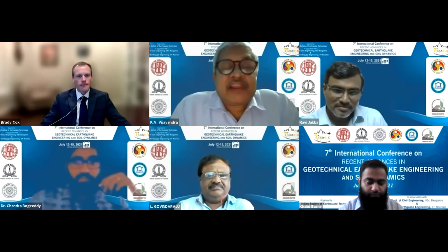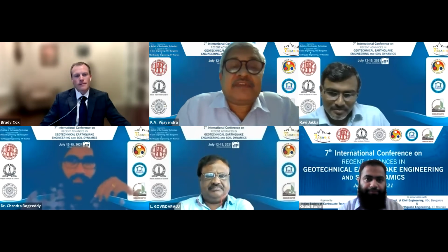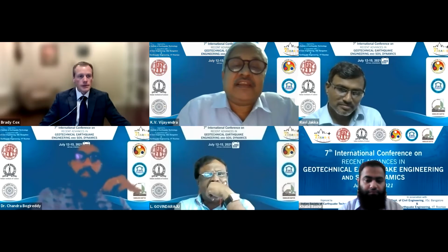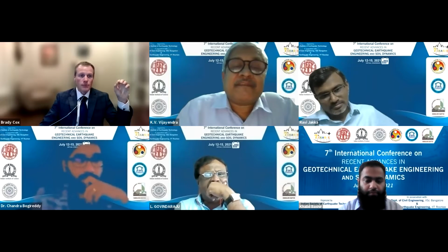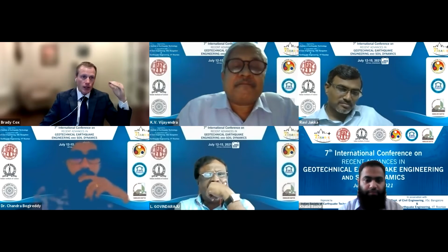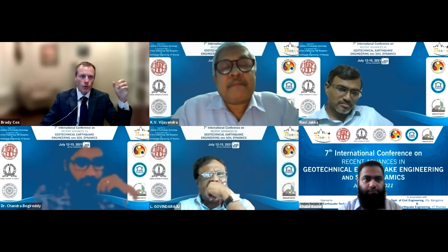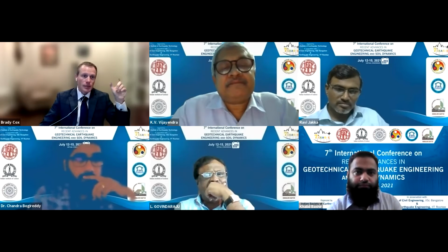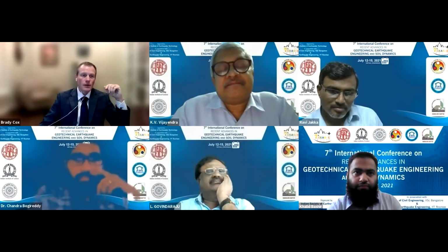Thank you. One last question, Professor Cox. In the shear wave velocity profile which you adopted to get the transfer function, what was the minimum damping ratio used? Was it from Stokoe and Darendeli? Yes, that's correct. When we did our normal 1D site response analyses without modifying damping, we used D-min from Stokoe and Darendeli, so it varied as a function of material type and confining pressure. D-min would typically have been on the order of 1% to 2%, depending on whether it was clay or sand. And when we modified damping using Rathje's approach, we would take that D-min and multiply it by a factor of 3 or a factor of 6 in order to bring down the amplitude of the fundamental mode peak.